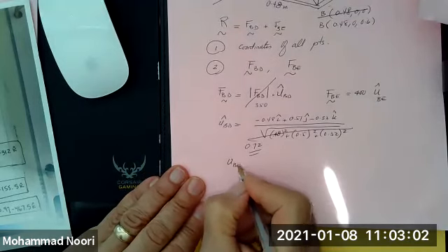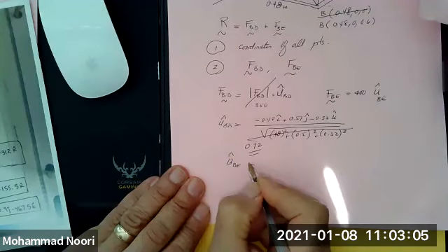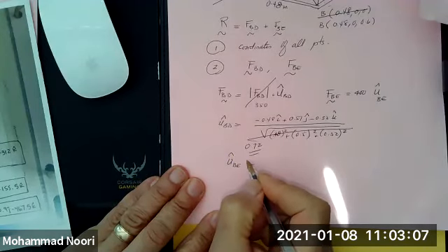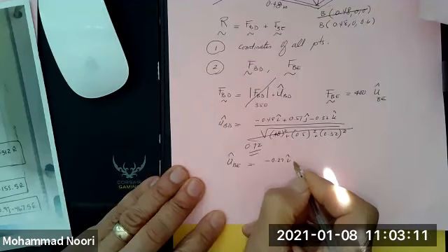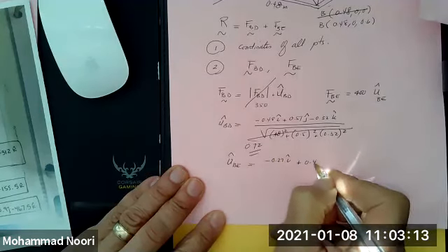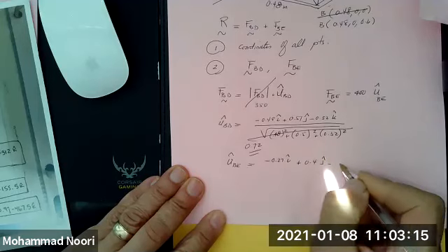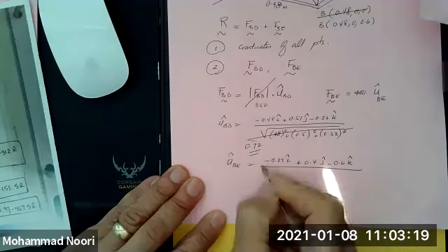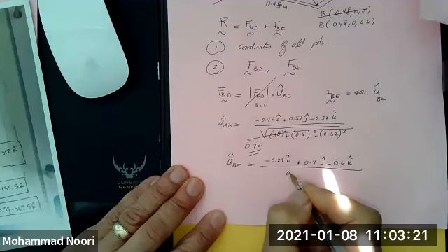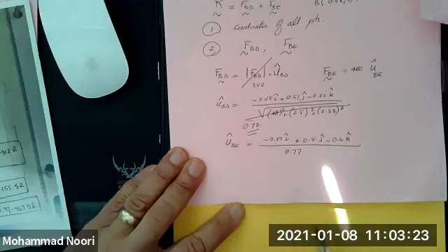And I would quickly write down, because I just want to give you the answer for this. If you do the unit vector of BE, you'll see that it comes out to be negative 0.27 I plus 0.4 J minus 0.6 K, and the square root of the sum of these squares comes out to be 0.77.